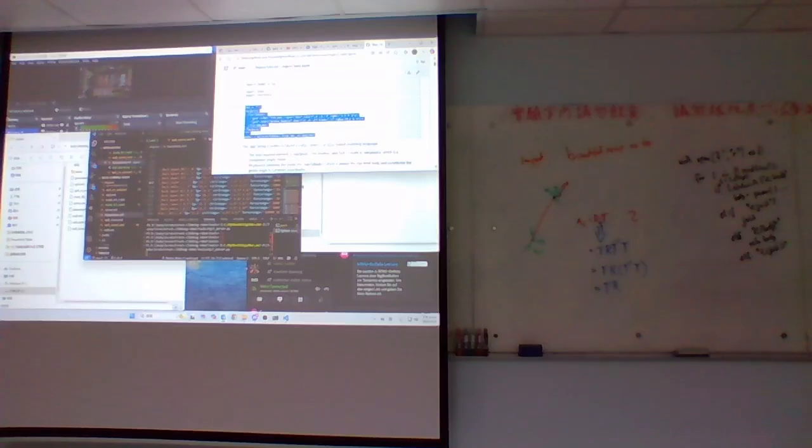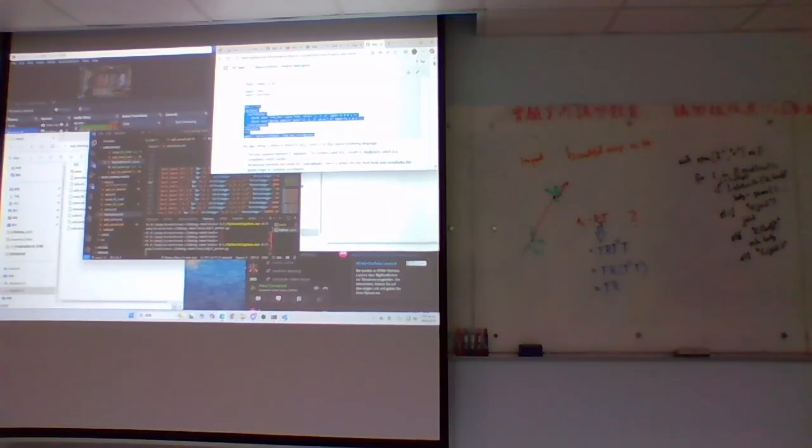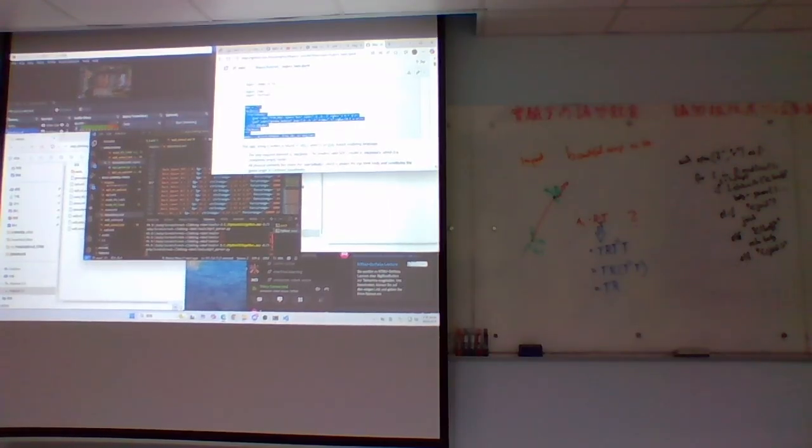friction. So does it mean the inertia is incorrect, because when you run the simulation, the robot cannot balance itself because the center of mass is not correct? It's on the impact, and it doesn't do any controlling. The actuator is just fixed. It just drops down. There's no control. You set it to all 0 degrees, and in that state, it just falls over. You should make it so it always hangs on the wall, right? I think that would be easier.